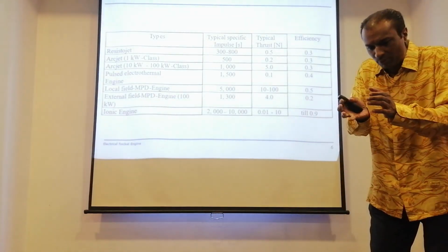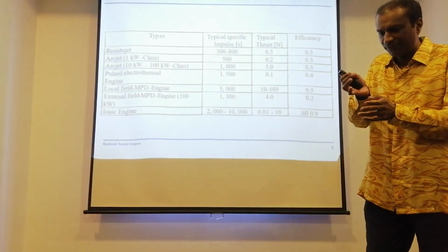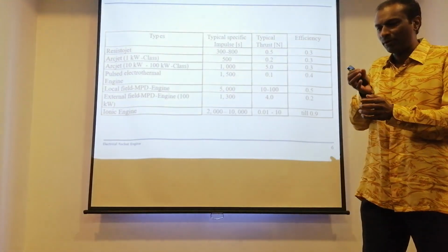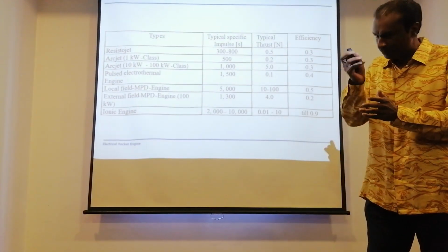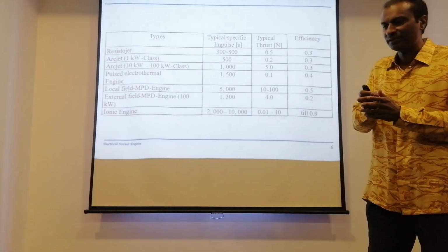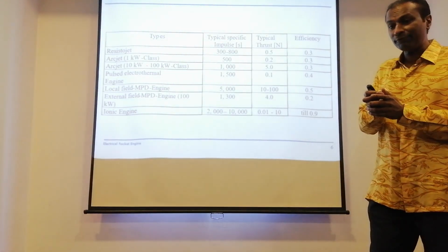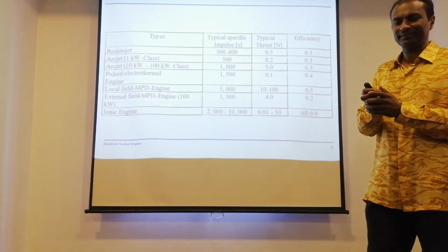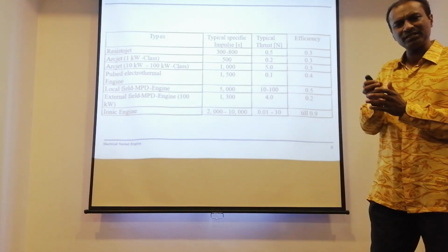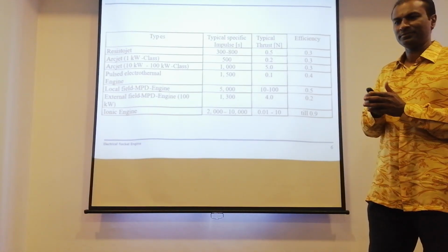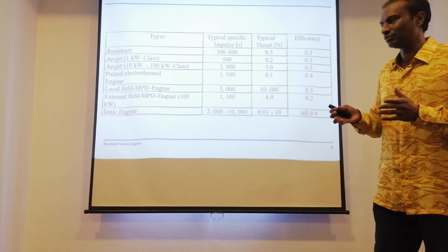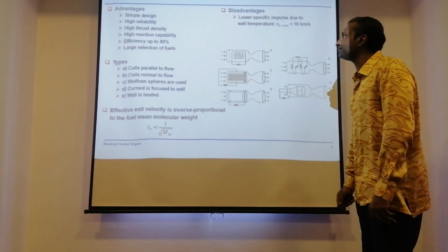That means for a very small engine, I put in a little fuel, it gives me a very small thrust, but so efficient a delta V because of its Ce. Ce is so high compared to my force. So it is efficient.